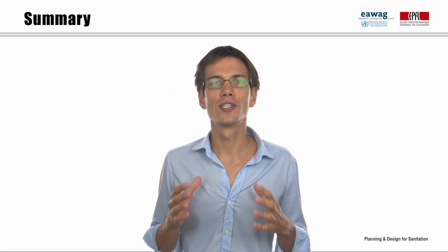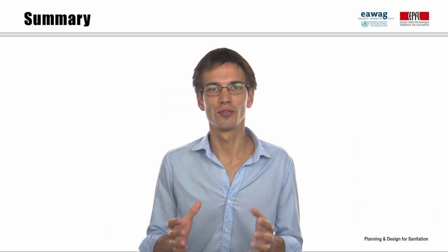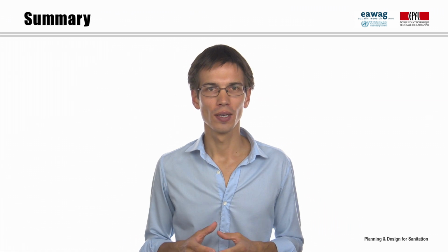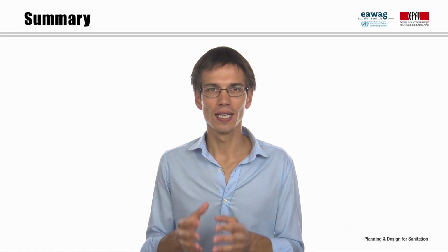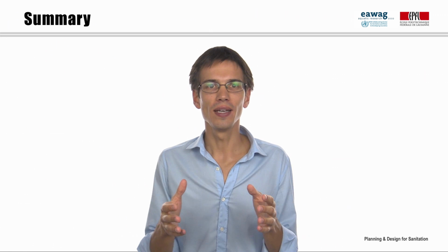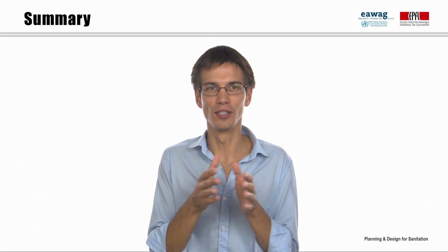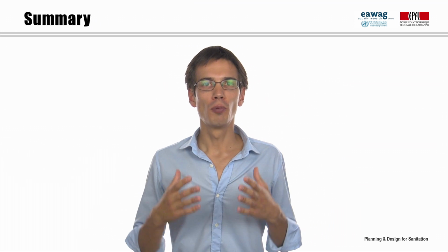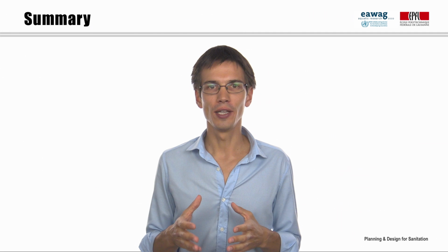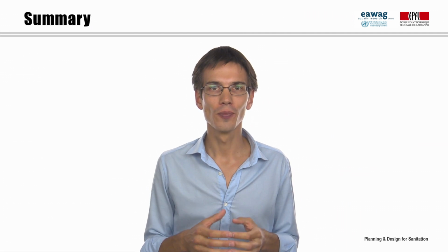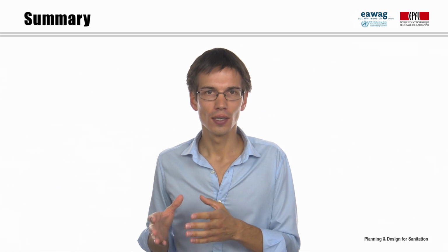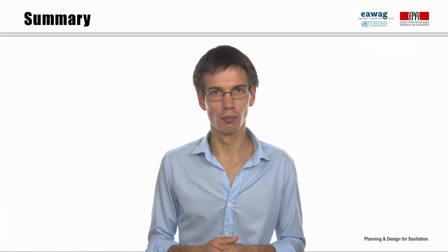To sum up, we saw that treatment is a succession of different steps, the main ones being the primary and secondary treatment. Pretreatment is a must as a kind of preventive measure, either at the household level, at the street level, or at the inlet of a treatment plant. Post-treatment is not always necessary and a pragmatic approach is recommended. The effluent quality should match the intended end-use practice or the quality of the receiving water body.